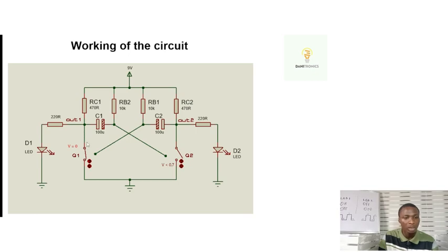And so you notice that this end of the capacitor and this end of the resistor are already connected to 0 volts. That's the ground, connected to the negative terminal of our 9-volt battery. So at this point, since it's short circuit, since it's closed, the voltage across this point will be 0 volts, because it's just going to serve as a straight wire.